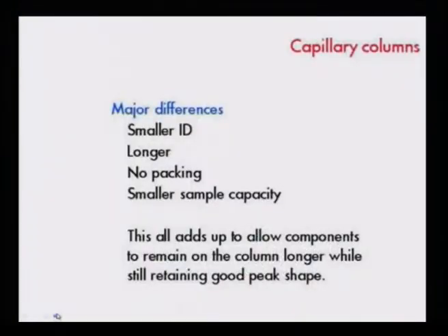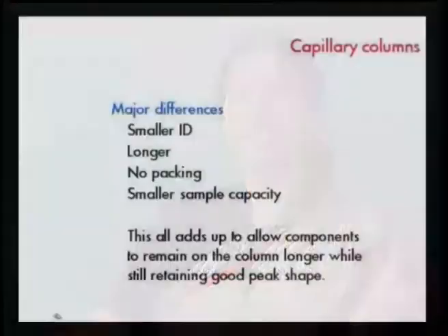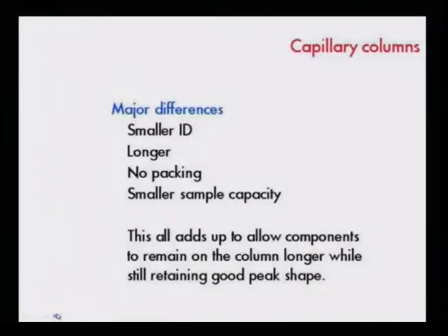Major differences between the capillary column and the packed column are that they are smaller in their internal diameter, ID. They are much longer in size. I said they are almost like 50 meters and they have been rolled up. Sometimes no packing material is used, or sometimes a very thin film of packing material is used.